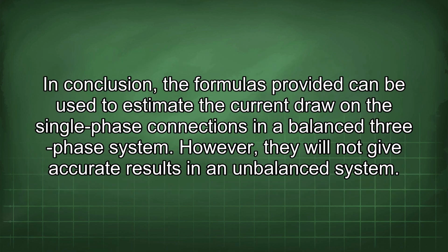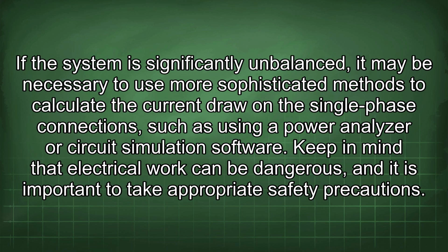In conclusion, the formulas provided can be used to estimate the current draw on the single-phase connections in a balanced three-phase system. However, they will not give accurate results in an unbalanced system. If the system is significantly unbalanced, it may be necessary to use more sophisticated methods to calculate the current draw on the single-phase connections, such as using a power analyzer or circuit simulation software.